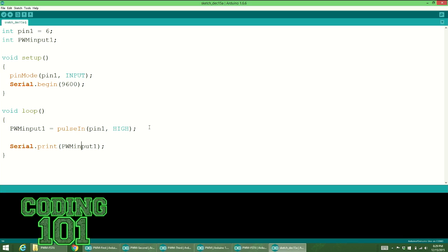And actually, what I want to do is I'm going to print line it so that it gives me a little bit of room at the bottom. Also, you've already seen this, so I'm not going to demonstrate it individually. If I just did this, the values would scroll by so ridiculously fast that you wouldn't be able to see it. So I'm going to put a delay of 200. It'll just wait 200 so that it doesn't go so crazy.